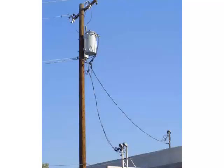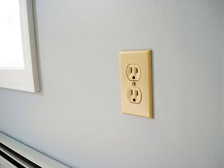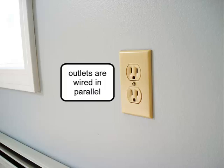Electric current is fed into a home by 2 wires called lines. Each line has a voltage of about 110 to 120 volts. These lines are connected to wall outlets in each room. The voltage is applied to appliances and other devices that are connected in parallel by plugs to these lines.